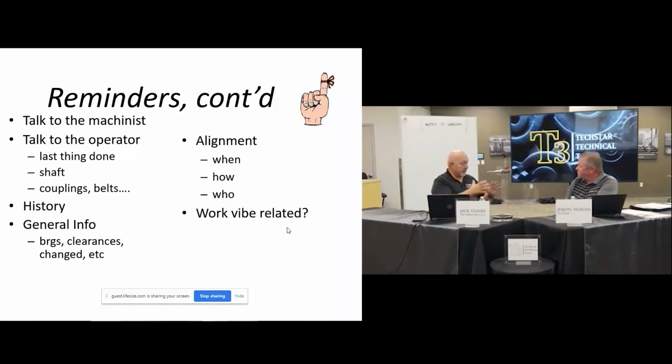All the shims had cracked and come off, and so naturally we shut that machine down before it came apart. And being a steam turbine, it was going to overspeed. Yeah. Which the other story behind that, the trip valve spring had rusted off. Oh, wow. So it might have been a near miss.